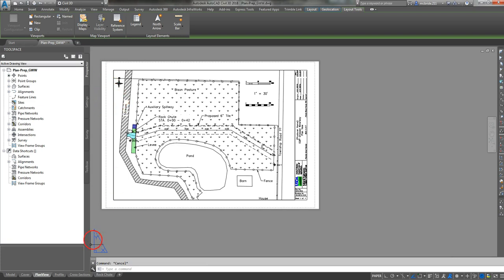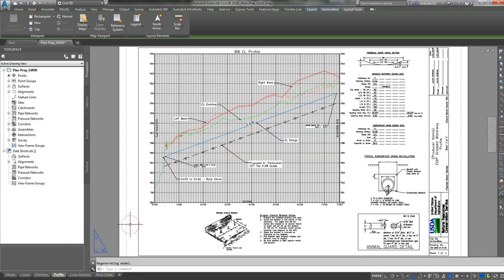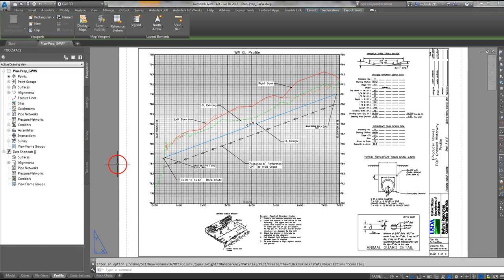That's it for the plan view. The third sheet is the profile view. So again, this is a profile we've already done. We've done it in one of the previous CAD webinars, but we've pulled it in using another viewport. And you can't see the viewport because I've hidden it. I've done this by setting my boundary for the viewport onto a layer which I turn off for this sheet.